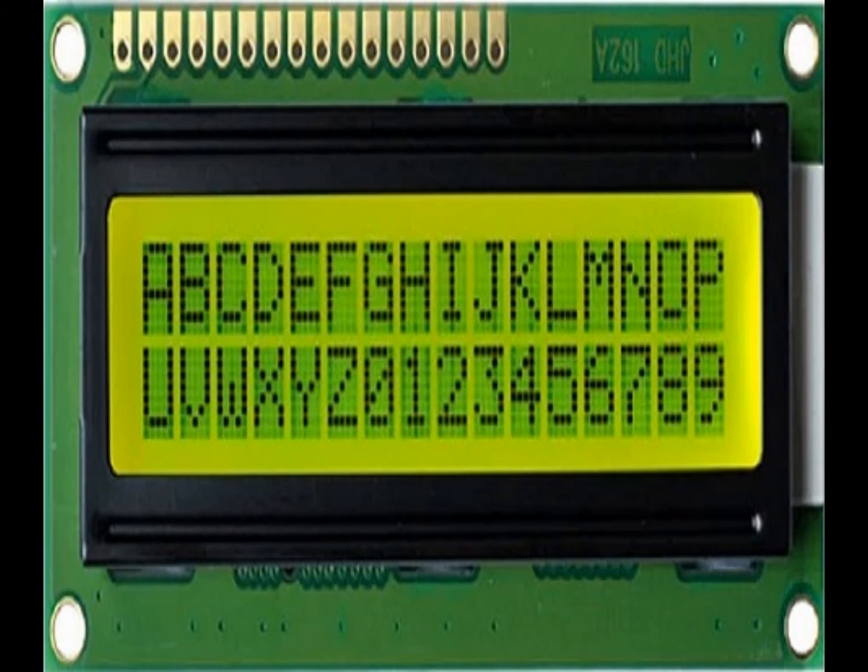This much information is more than sufficient for the current time being. After all, we don't have to worry much about how the LCD works, as the liquid crystal library available on the Arduino IDE takes care of almost everything. From Arduino's official website, you can find and see the functions of the library which enable easy use of the LCD. We can use the library in 4 or 8-bit mode. In this tutorial, we will be using it in 4-bit mode. In short, we will just use 4 of the 8 data pins.